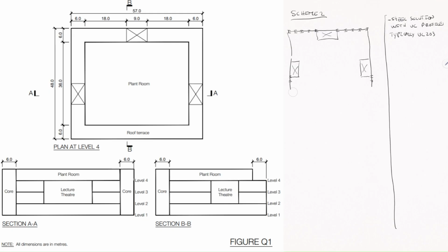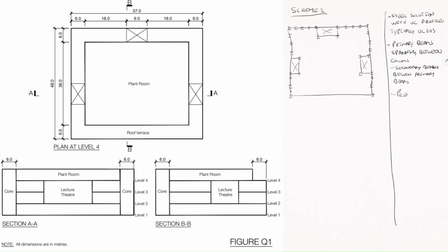Once I have all of that, which is normally 2 plan views showing the different column arrangements at different levels, and 2 sections, or 1 section and 1 elevation, showing load transfer and also lateral stability, I can go to the next scheme or the next option.